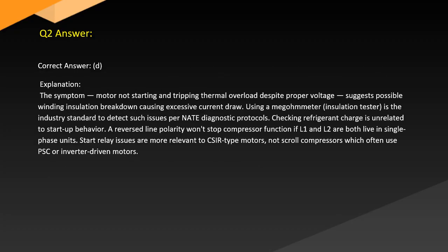Answer. Correct answer, D. Explanation. The symptom, motor not starting and tripping thermal overload despite proper voltage, suggests possible winding insulation breakdown causing excessive current draw. Using a megohmmeter insulation tester is the industry standard to detect such issues per NATE diagnostic protocols.